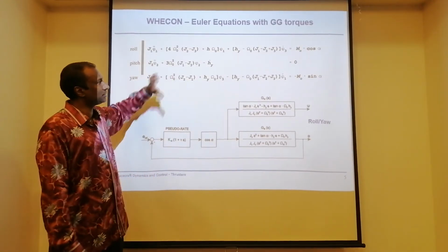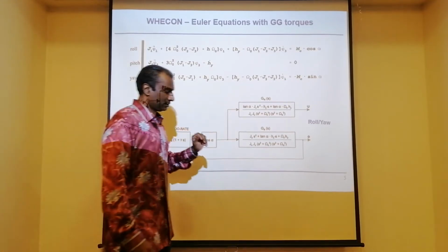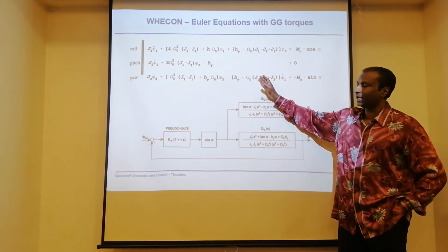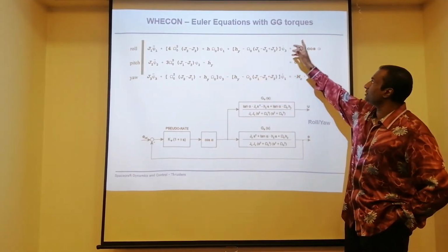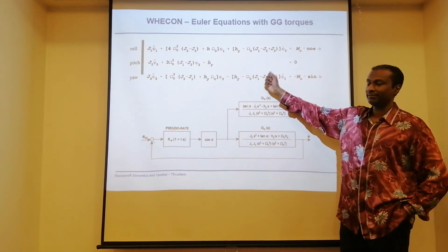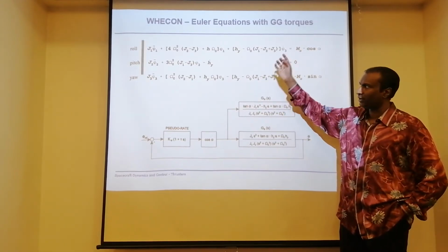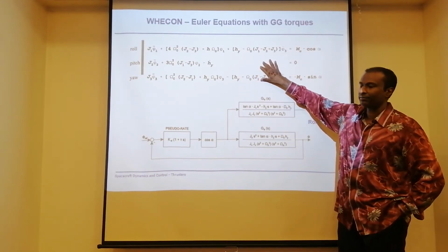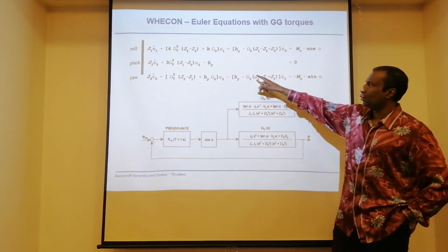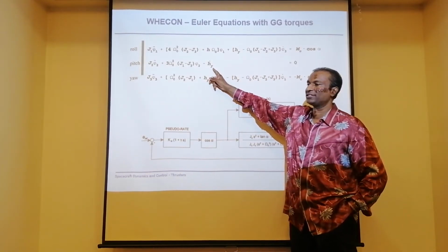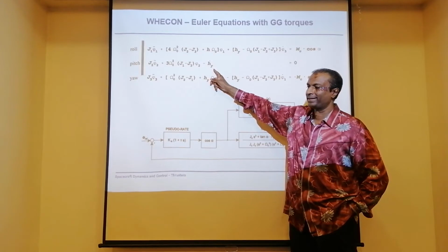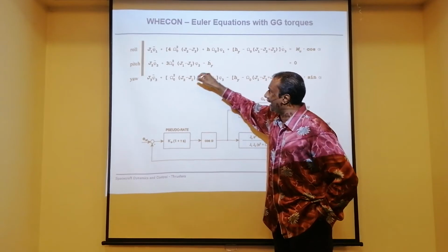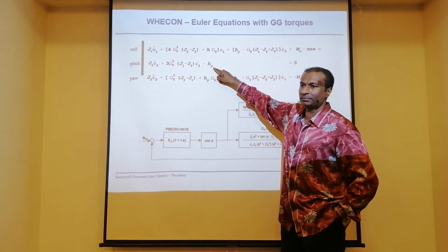Okay, here is what is a bit interesting. Now, remember this. This is the same equation that we have developed, and you have been using. This is with gravity gradient torque. That means, remember the gravity gradient component that we have inserted. This is including the gravity gradient component and with a wheel. And so H dot will be a torque. Momentum will torque. So which means that my pitch axis here can be controlled by my wheel.